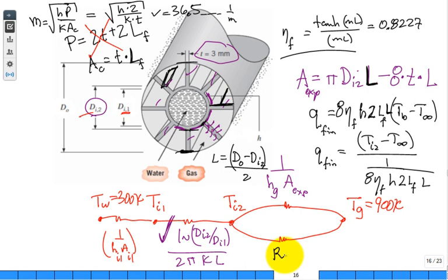Now, what I encourage you to do is go ahead and calculate a value of this resistance, that resistance, this resistance, this resistance. Actually, what would be the units on each of these resistances? Isn't it degrees C per watt? And then, what should you do to these two resistors? Combine them because they're in parallel. And then what do you do with this one and that combined? You add them in series. So go slow. I think you'll work it out.